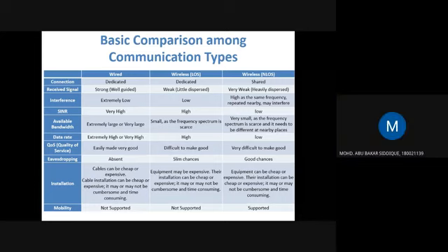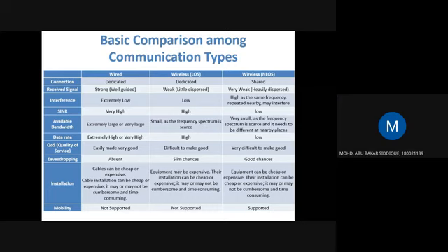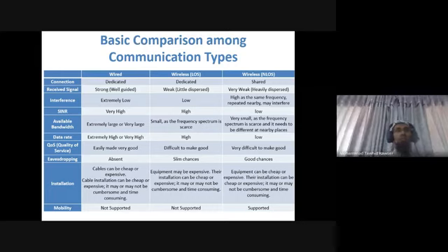These signals interfere with each other, but only when they are not time aligned. These different multipaths take different delays. When the delays are different, then they interfere. We'll later show that it is called intersymbol interference, ISI. But if two versions arrive at the same moment, then it is not interference. Then you sum up the signal, and that will be advantageous for you. But intersymbol interference can be problematic for you.